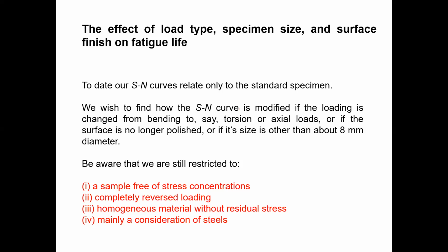If you change the specimen size, that's why in the test, if you remember when I explained, I told you the dimension should be 8 millimeter. If you change that size without fixing the dimension, the fatigue life will change. Then you can't compare the material's strength, because the fatigue life varies due to specimen size, not because of the material. So that's why we need to fix that parameter. As for surface finish, that's why we use mirror polish.